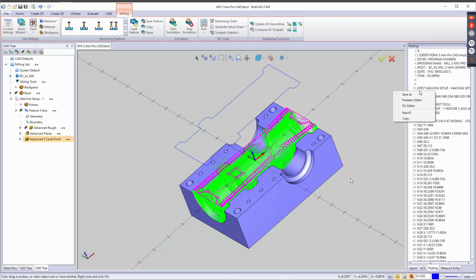Do not save this G-code directly to the desktop. If you do, the file possibly and most likely will get corrupted. There's rewrite issues on there. You can put a folder on your desktop and save it inside that folder on your desktop. That is fine. It's protected now. But if you just save it directly to the desktop, there are rewrite issues on there, and it will corrupt that file.